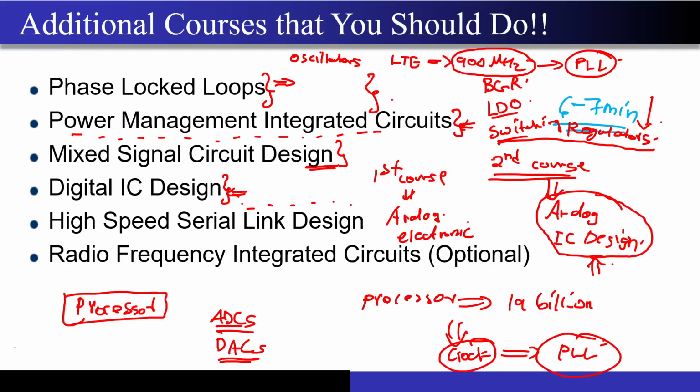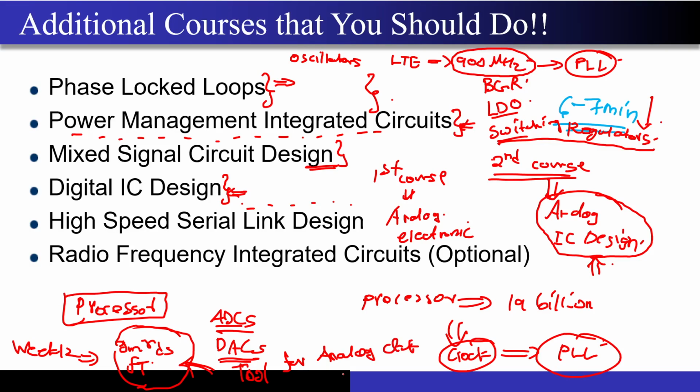The last lecture, week 12, sir had shown you some plots, gm/ID, then fT and all, correct? So whatever plots he had shown you, that forms a basis, that forms a tool for an analog circuit designer. So remember those curves that sir had taught about: the intrinsic gain of the transistor, the fT, how the VDSAT varies with VGS minus VTH and all.